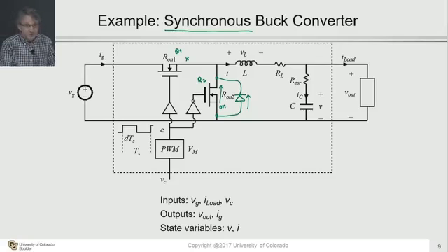One little question, since we are discussing the review of the Intro to Power Electronics material, is why would we want to use here a synchronous rectifier, a MOSFET, instead of just a plain diode? Yes, so the point of using this MOSFET here is that the R-on resistance of the synchronous rectifier, R-on2, times the current that would be flowing through that synchronous rectifier from source to drain, would be less than the diode voltage drop, and so that implies reduced conduction losses.